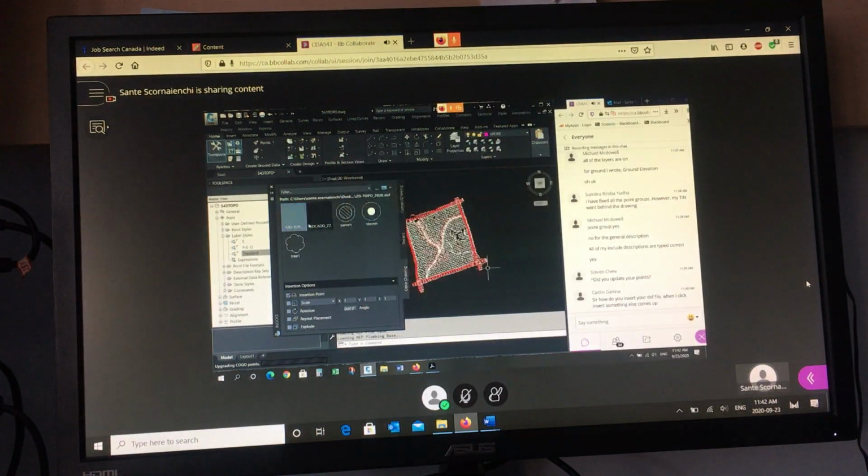Okay? And if you don't want to see it as an image, you can look at it as just a list. So it appears in this dialog box. It still hasn't gone into the drawing. Then you can set your parameters here. So make sure everything is on. You want the insertion point to be by default 0, 0, 0. You want the scale to be 1 across the board there, X, Y, and Z, and you want the rotation angle to be 0. Then to bring it into the drawing, you just double click on this.